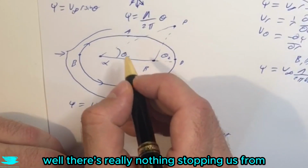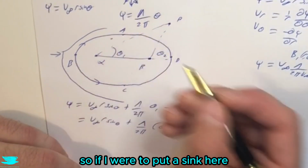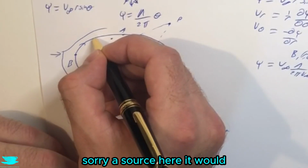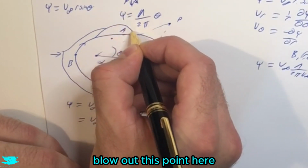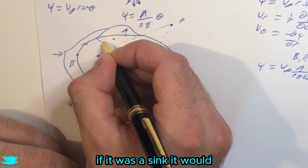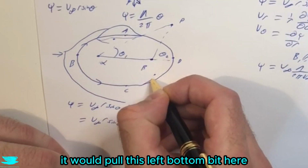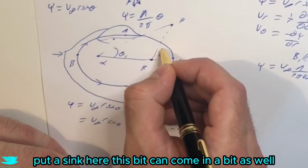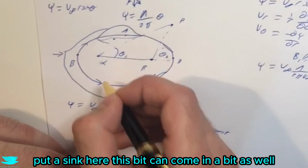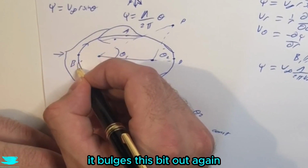Well, there's really nothing stopping us from putting other sources and sinks around this object. So if I were to put a sink here, a source here, it would blow out this point here, and it would actually change where the stagnation point is. Alternatively, if this was a sink, it would pull this section in a bit more. If I were to put a sink here, it would pull this left bottom bit here, put a sink here, this bit again comes in a bit as well. If I were to put a source right next to the other source, it would bulge this bit out again.